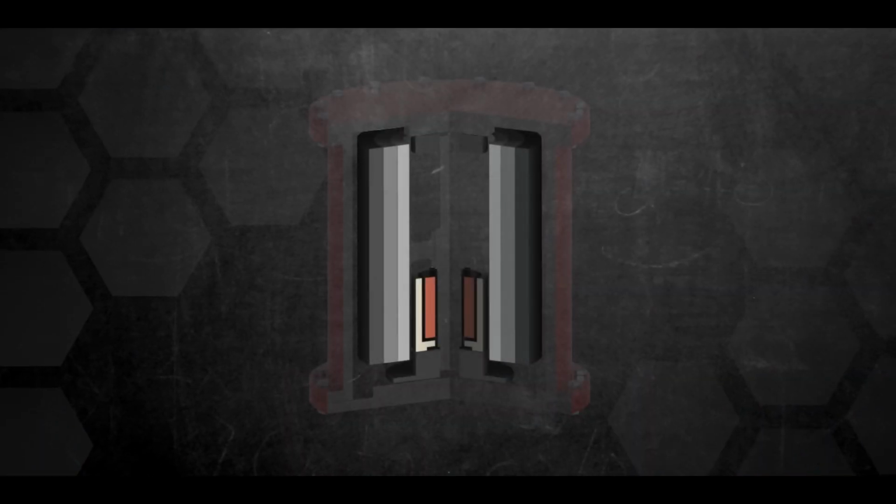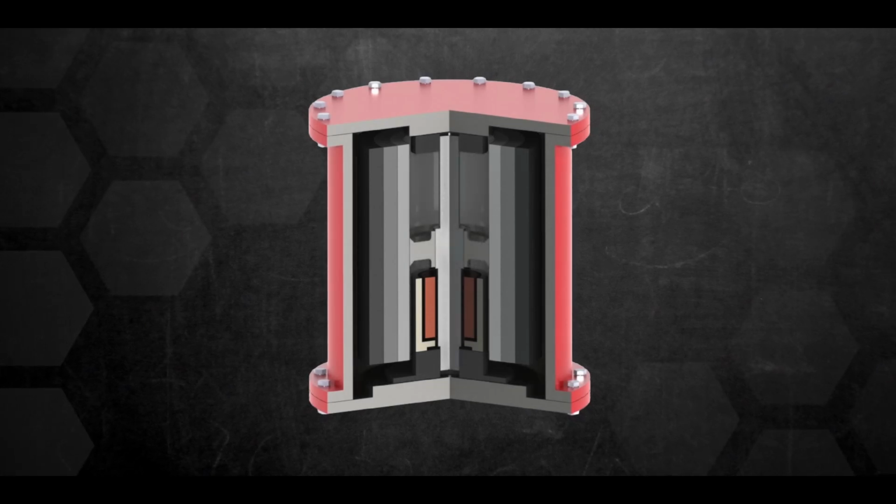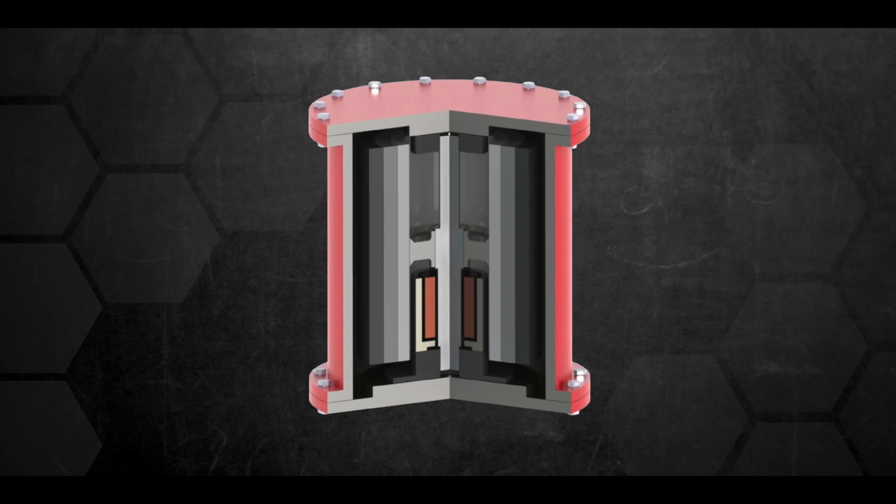Since then, several improvements have been made to flywheels in order to increase power storage capacity with safe operation. Flywheel energy storage systems, or FESS, are essentially composed of a few key components besides the flywheel and electric motor. It includes bearings, an enclosure, and a power electronic converter. FESS have bearings to support the rotor and resist against forces to maintain its position, which allows it to spin at the high velocities, but there's a downside there.